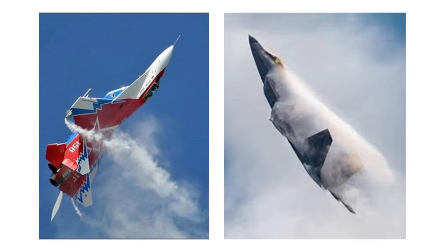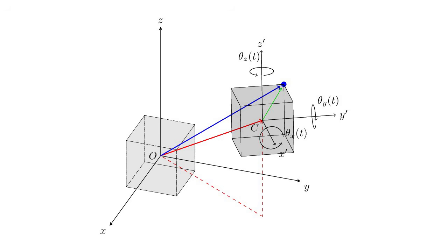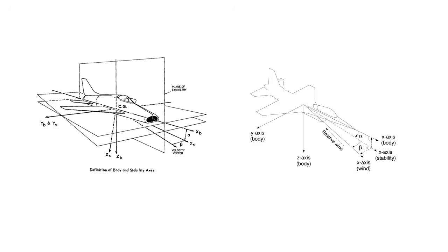The analysis of aircraft stability and control is a fundamental result of rigid body dynamics. Rigid body motion consists of translations and rotations about the CG, and these can be described as 6 degrees of freedom: forward and aft motion, upwards and downwards motion, and lateral translations, as well as pitch, roll, and yaw.